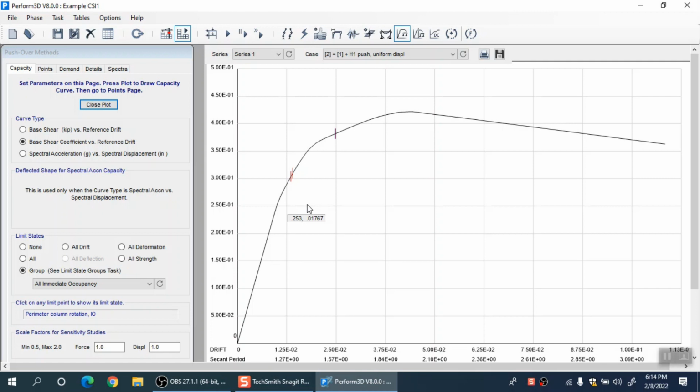Now for example, you calculate or estimate the peak roof displacement produced by the future earthquake from any other method, which currently you don't know, but there are methods available for that. So let's say that number comes out to be somewhere here at my cursor. Which means that the future earthquake is going to push your building up till this level, right. If you have that curve and all the markers on it, all the damage levels, then you can directly tell that under a future earthquake your perimeter columns are not going to go beyond the IO level, because they are somewhere beyond that point, right.